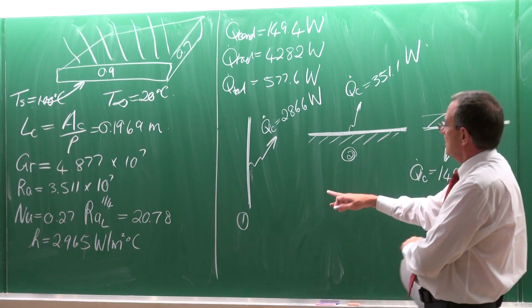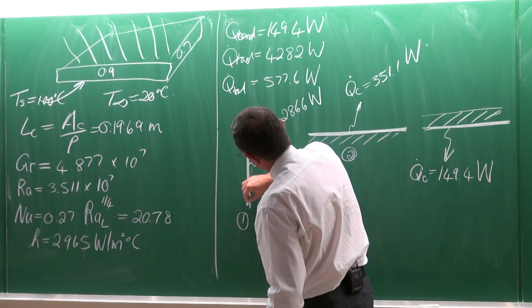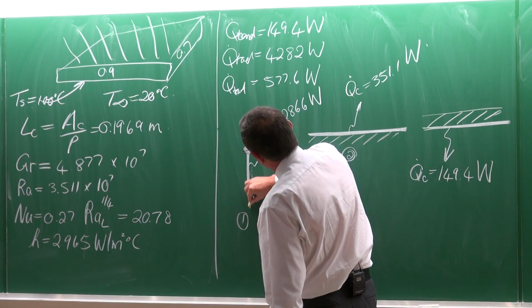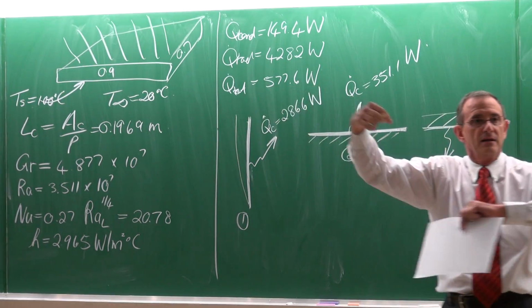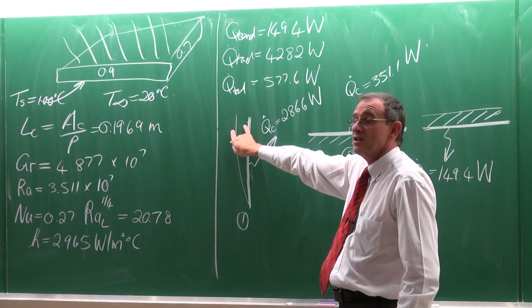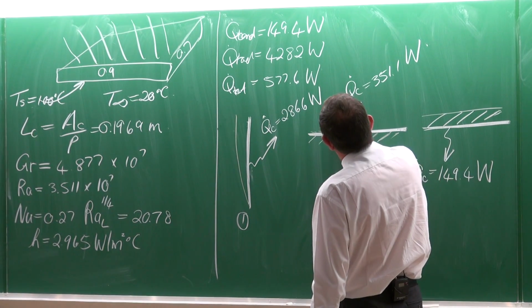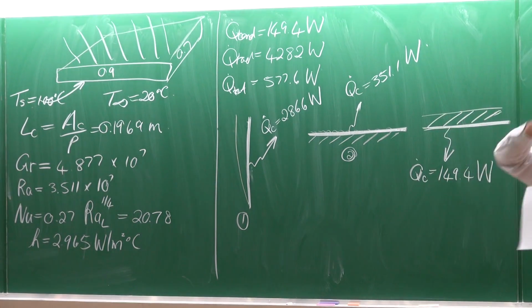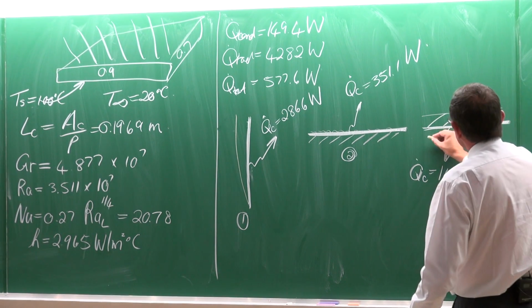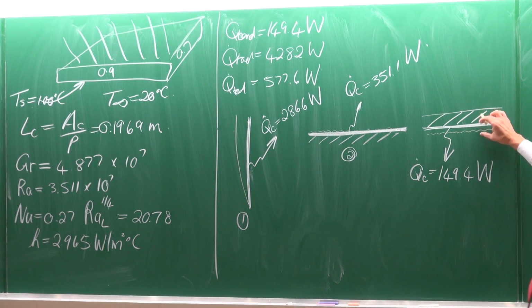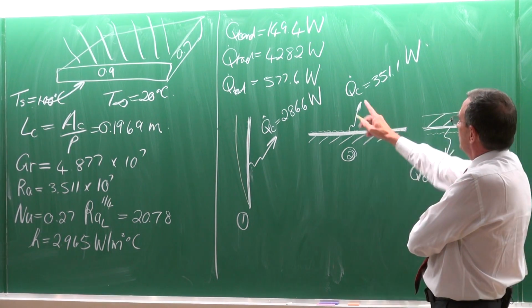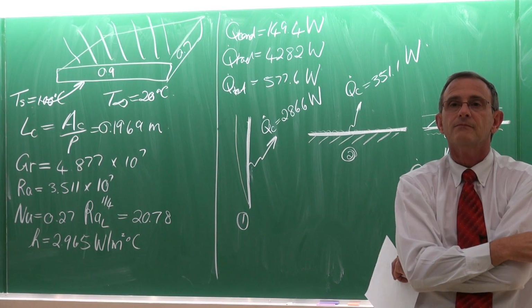but it clearly illustrates the importance of the thermal boundary layer. This thermal boundary layer, as I've explained at the beginning, is going to form like that, and it becomes thicker and thicker. And the thicker it becomes, the lower the heat transfer coefficient will be. In this case, the thermal boundary layer is going to break up all the time because of the convection just going up. And in this case, it's going to build up here. You're going to have a thick thermal boundary layer at the bottom. Okay? And that's the reason why the heat transfer rate from that plate would be the highest.